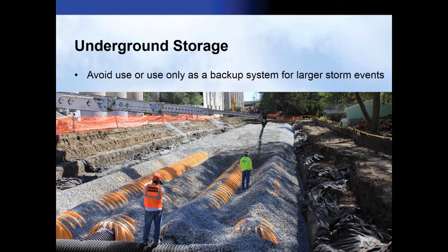So, quick thought about underground storage. Underground storage is a valid green infrastructure practice. I wouldn't call it the best, but it's valid. There are times when designers use this as a cookie-cutter go-to design option when other, better surface green infrastructure practices could be used. So we shouldn't use underground storage as a fix-all solution because it still conceals the treatment,